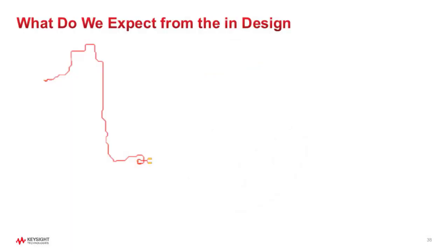the SI Pro window will show up, as well as a 3D view of the board. You can do it different ways. You can look at the trace, the USB trace in the middle. Deactivate the components, and just show only the trace. And here are the other layers. You can zoom in and zoom out. And here is what it looks like with only components.